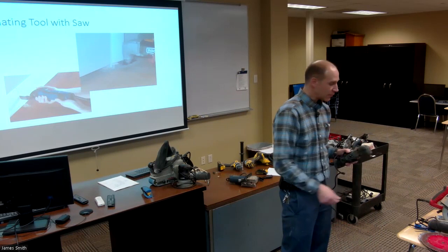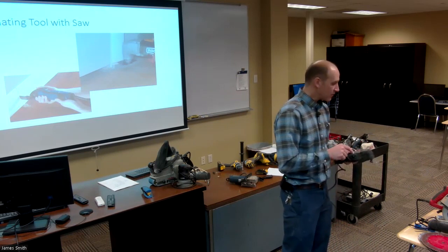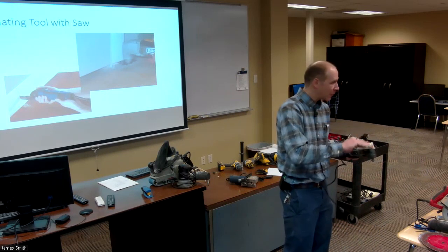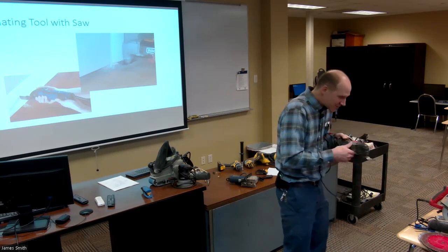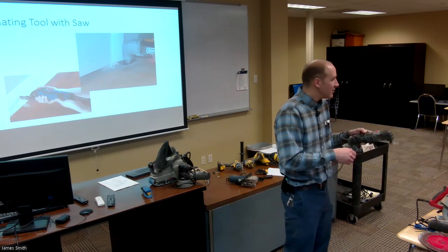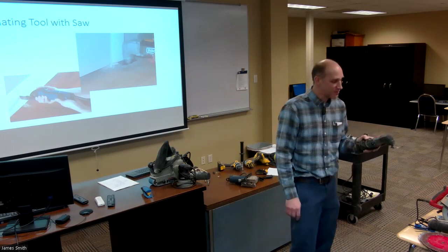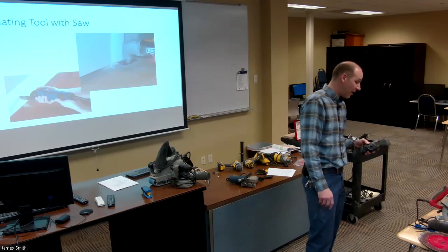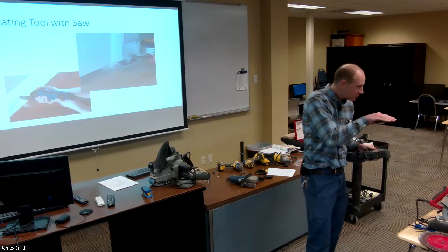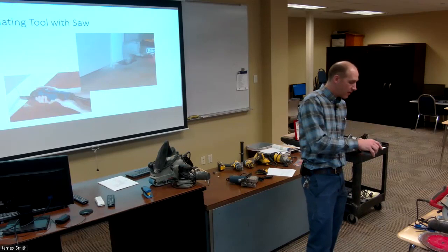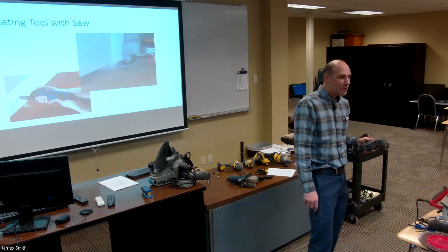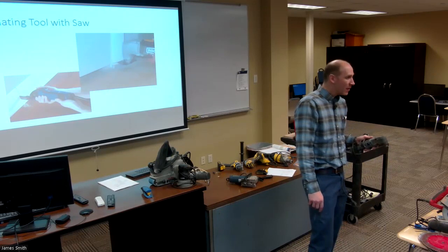And what do I use this for? Well, the main thing I use this for is when I'm installing flooring and you need to shorten up your door casing, just going in there and kind of shortening that up. It's pretty phenomenal that way. Isn't that kind of like vibrate or something? Yeah, it just oscillates real short. And that's the reason why it doesn't remove material very well. But boy, it burns right through it.